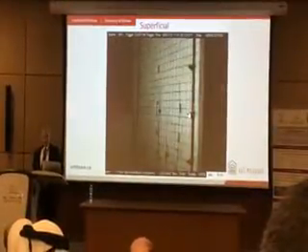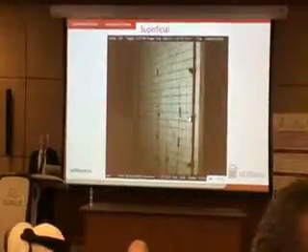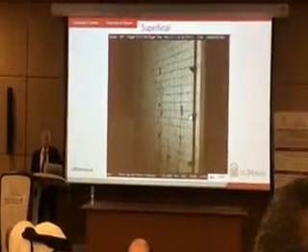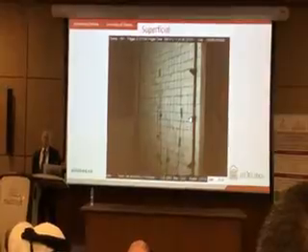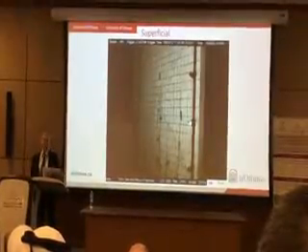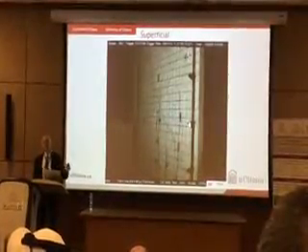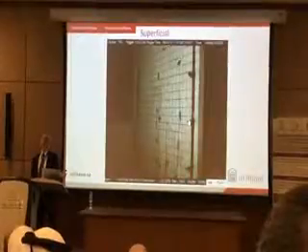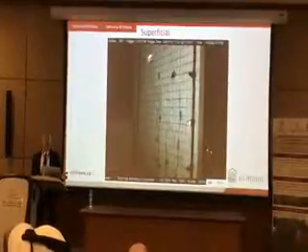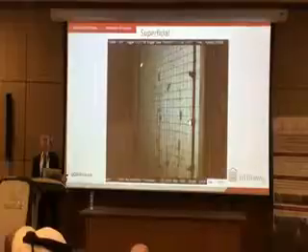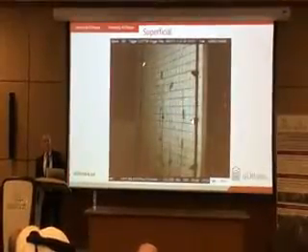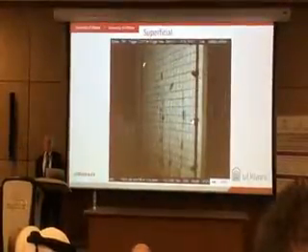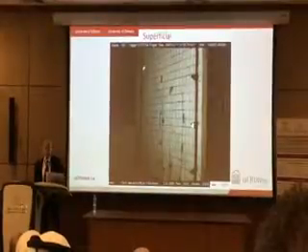Now, here is a slab of a parking garage that we tested. As you can see, this is the second shot, and we marked the cracks. It deflected, it bounced back. There's no permanent deformation, which means there's no yielding. This is okay. You can continue using the building. It could either be immediate occupancy or it could even be operational because damage is superficial.